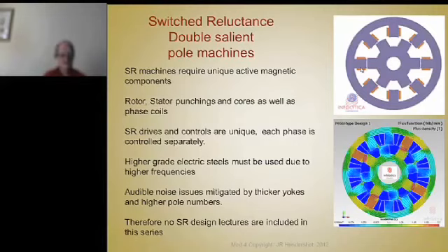So the machine is very simple. The coils are simple. They're wound around the stator teeth. There are no windings on the rotor at all. Some early proponents of these machines said the rotors are cool, that they don't generate heat. That's not really true. They do generate heat due to eddy current and hysteresis losses, because as you rotate this and attract those poles, you're magnetizing and demagnetizing those poles, and you're actually even reversing the polarity of the poles as you switch and go around. Not on every switch, but at least once per revolution, you're reversing the polarity. So that causes hysteresis losses.